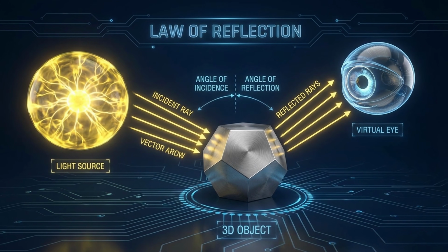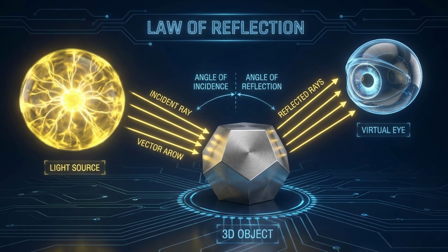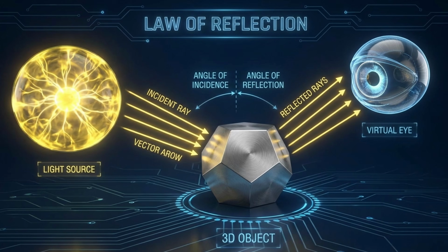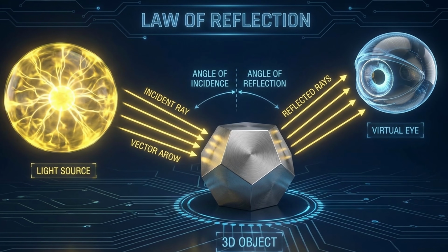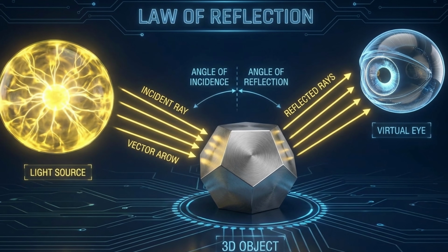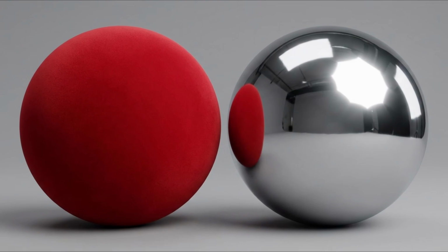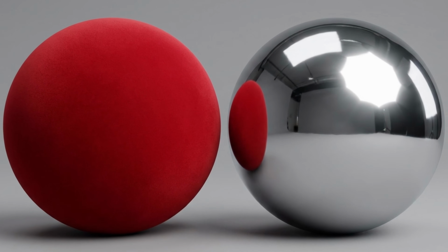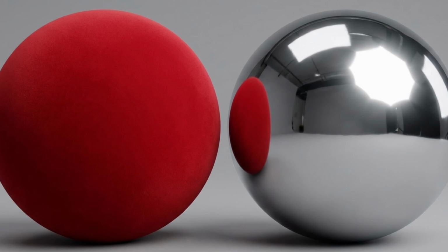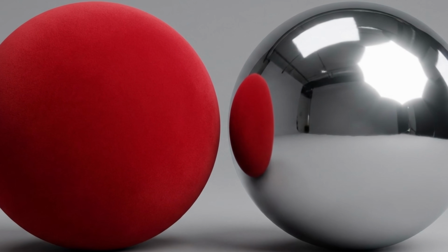This dedicated silicon continuously calculated distance and direction vectors from virtual light sources to the three-dimensional objects, and subsequently from those objects to the perspective of the viewer. This allowed the hardware to perform real-time calculations for both diffuse and specular lighting.